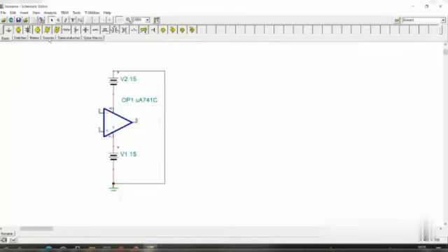So for giving the input, you have to take the sources. In this source you have a voltage generator. I told you whenever you need to give a sine wave. So now we are going to give an input as a sine wave, and you need to check the output at the input point at 2 and the output point at 6. That is what we are doing.